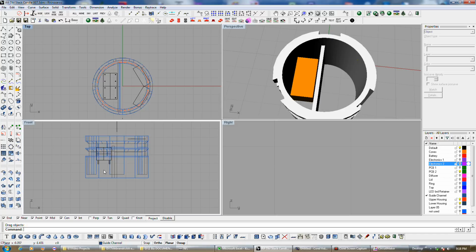What I do is I pre-solder the wire leads onto the relay terminals that I'm interested in, and just stick it up in there and hot glue gun melt it. I could apply some glue on the top, just drip it in on the top here, and then maybe a couple of little dabs in the corner here. That'd be enough to hold the thing in for this prototype. But at any rate, that kind of solves that little problem, so that's groovy.